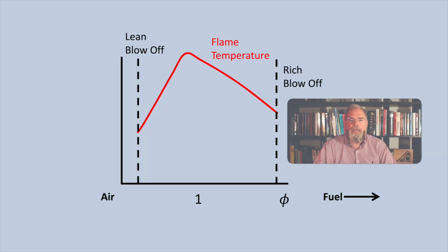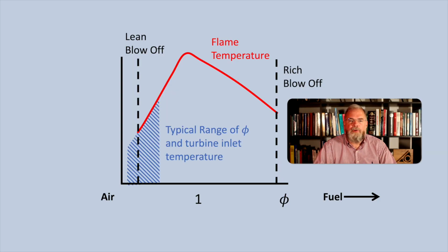However, because NOx emissions are exponential with equivalence ratio, just an aside, NOx formation is not strictly speaking exponential with equivalence ratio. As I've said before, NOx formation is exponential with temperature. However, at the range of equivalence ratios where premixed combustion takes place in a typical gas turbine combustor, the flame temperature is close to linear with equivalence ratio.